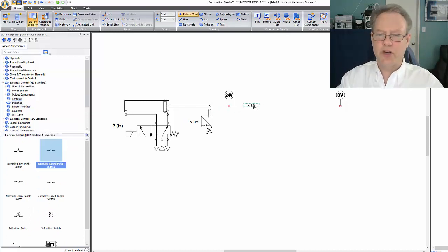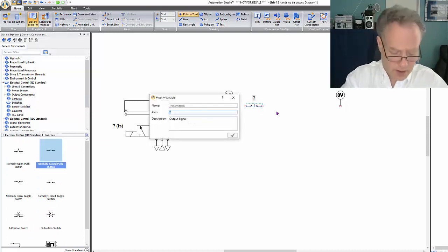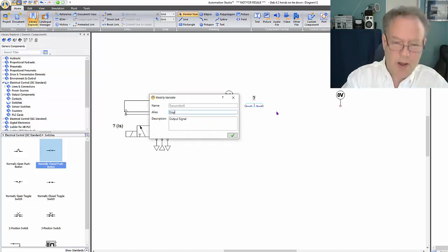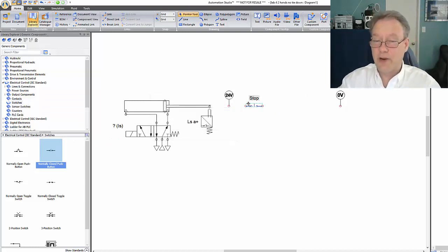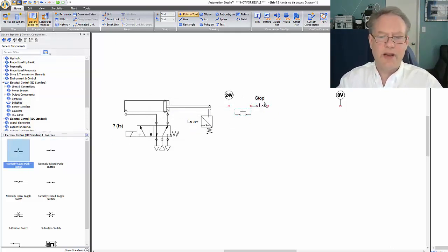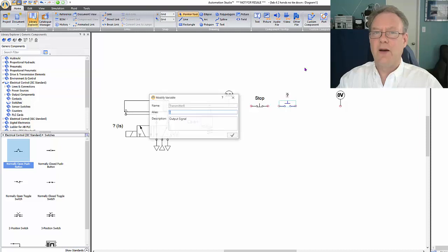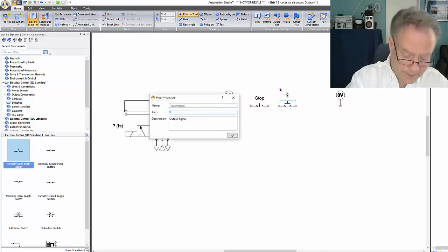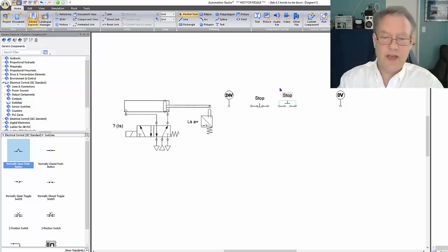What I do is I always put my termination contact first on my rung. Now I'm actually going to end up putting another termination contact in here that's going to be from my LS A+. So putting a little room in there. I never put anything between my holding circuit and my relay, and the reason for that is because it makes it easier to wire it up.